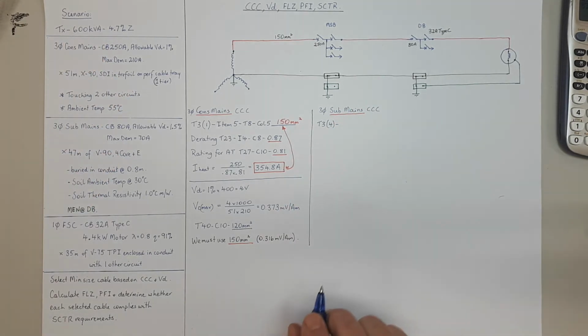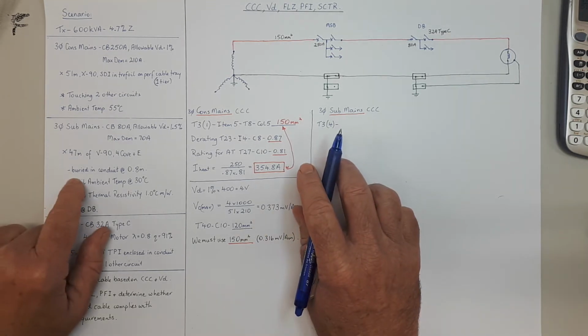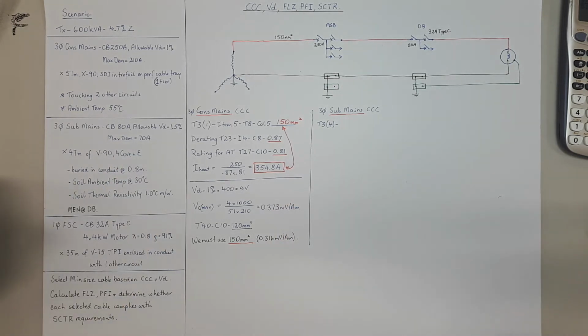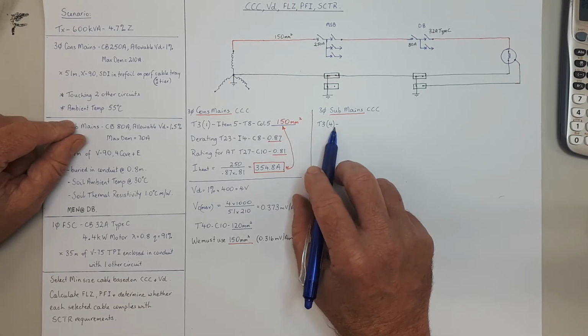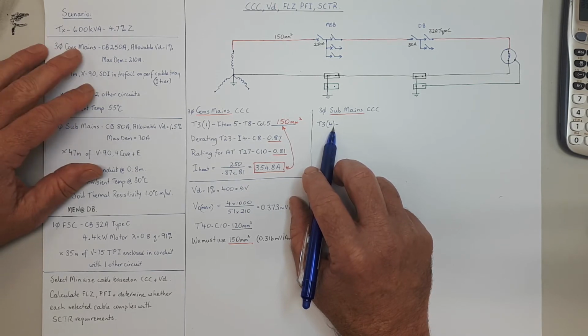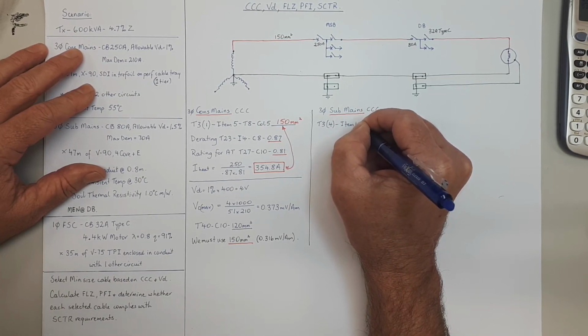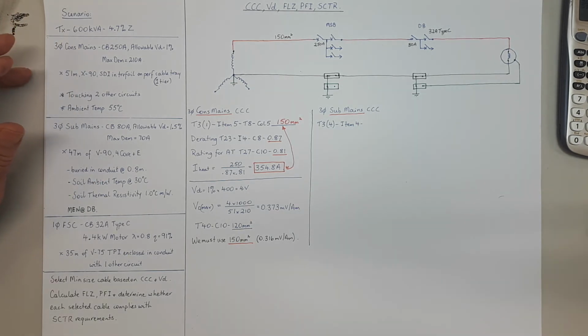And of course if we go to table 3.4, have a look there, turns out that we're looking for a 4-core on Earth. So of course they won't mention 4-core because one of the cores is neutral. We're only interested in, it's going to be a 3-core cable we're looking for. So we scroll our finger down, we find it's item 4 is what we're interested in. Item 4, and running our finger across, we find that we get table 13 or 14.